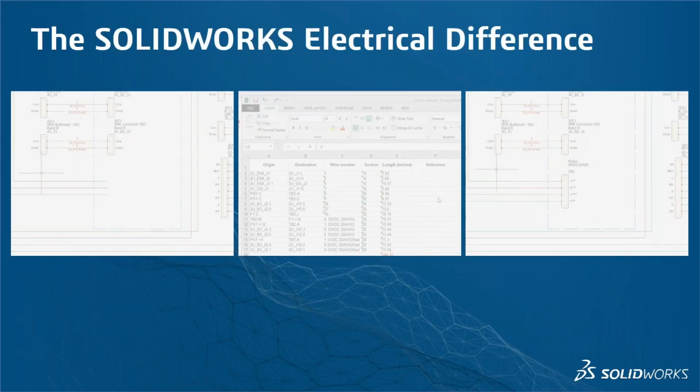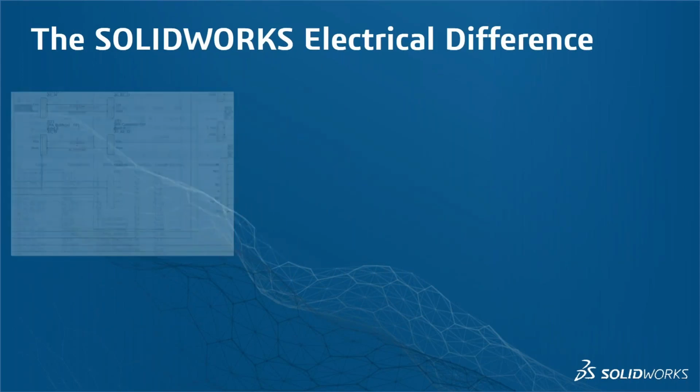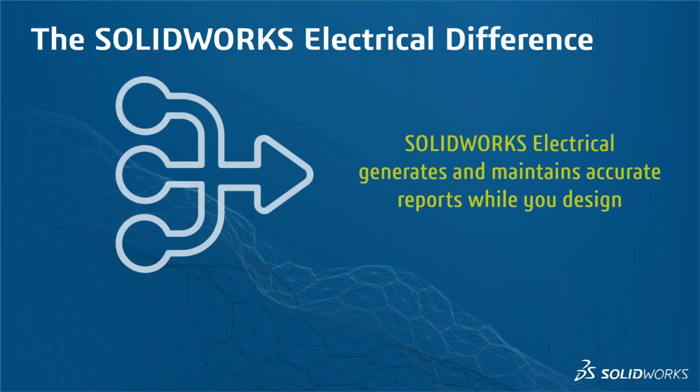Well, what SOLIDWORKS Electrical allows you to do is take a lot of that back end reporting and auditing and bring it up front while you're doing your design. So the design itself may take a hair longer, because when you drop in a block or a symbol, you're going to be adding metadata to that information. But on the back end, you're not going to sit in front of Excel for 6 days making sure that you've got all the right pins for your connectors.